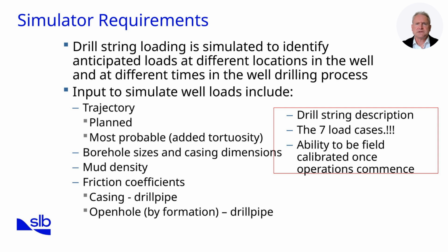Importantly, once drilling starts, simulators can be field calibrated by comparing predicted hook loads and torques with actual measurements. This improves accuracy and makes the tool dynamic, helping engineers update designs in real time. In short, a simulator is not just a planning tool, it's a living model that evolves with the well, ensuring overload design is not theoretical, but grounded in measured performance.